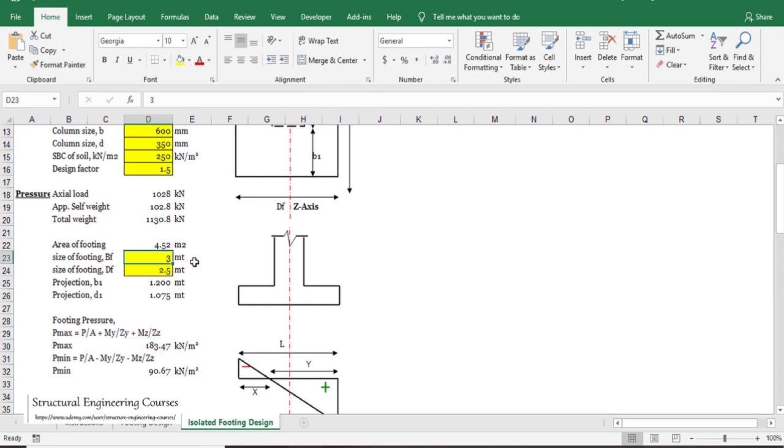So what we can do, let us say we can go by 2.5 by 2.25 here. Then also there is a warning. So 2.75 by 2.5. So in this case we can see that now it is somewhat okay. So against 250 we are now getting 227.73 kN per meter square. So this type of difference is manageable and desirable also, but otherwise as compared to 250 if we only give a footing pressure of 150, that is a highly over designed foundation. So now we can stick ahead with 2.75 by 2.25 meter foundation.